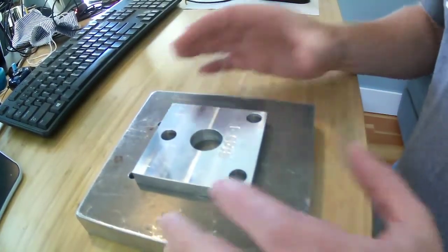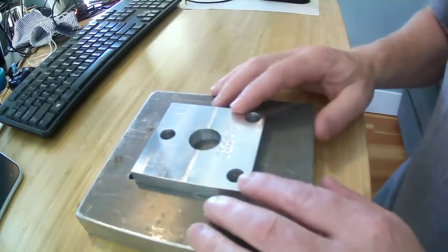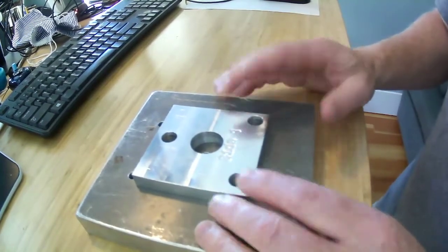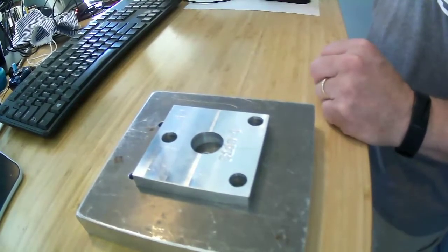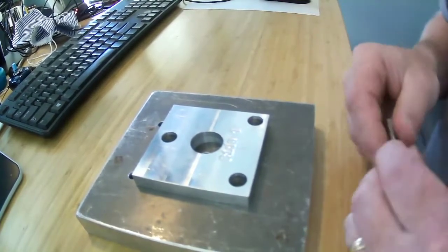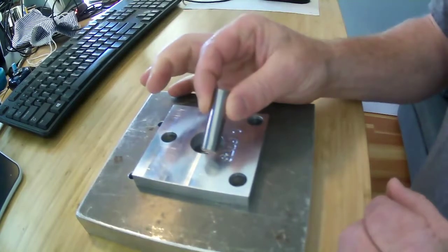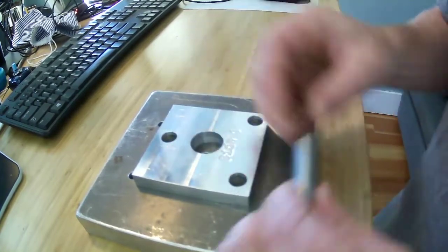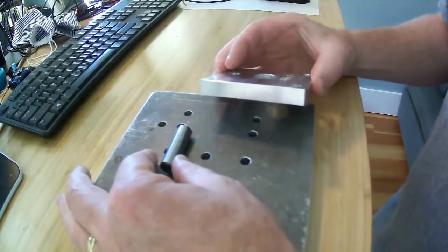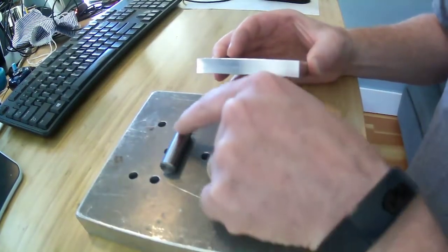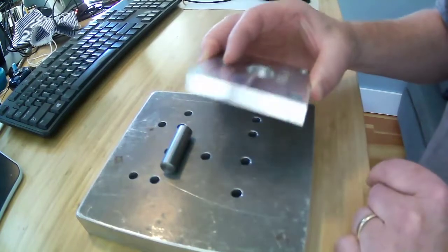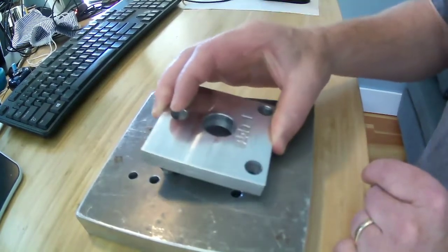But I don't want to be subject to whatever somebody else has decided. I want to make it only touch at 3 locations. Well, I have an idea. If I use a cylinder, a cylinder and a plane contact at 2 points, and it contacts somewhere along the line that is the intersection between the cylinder and the plane.